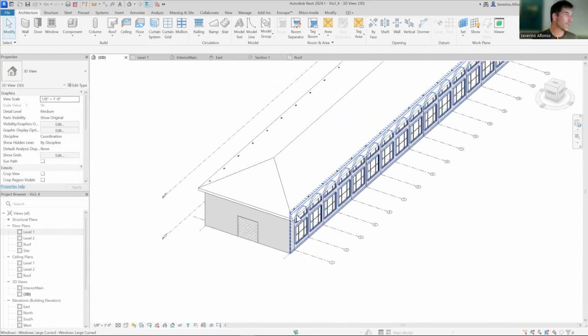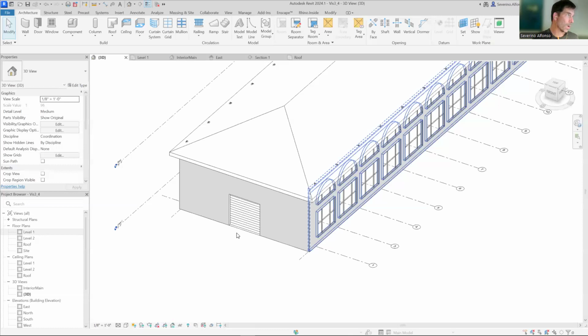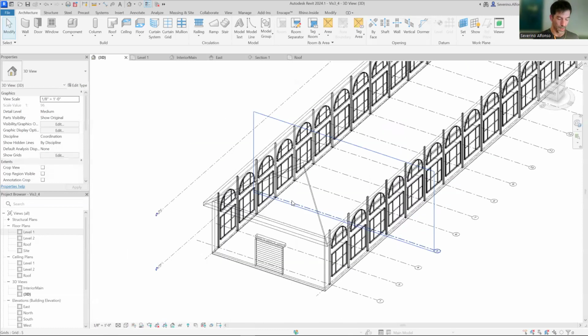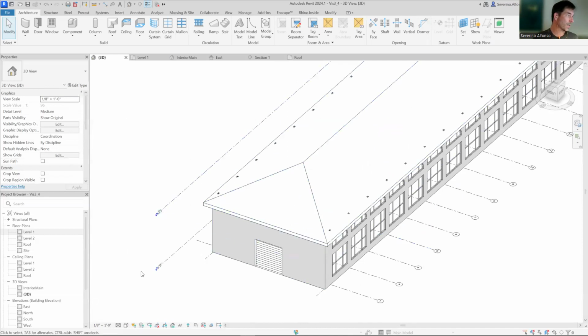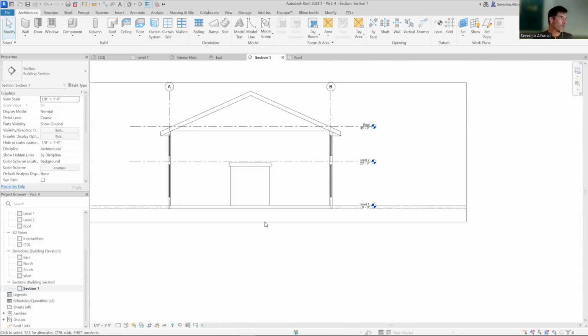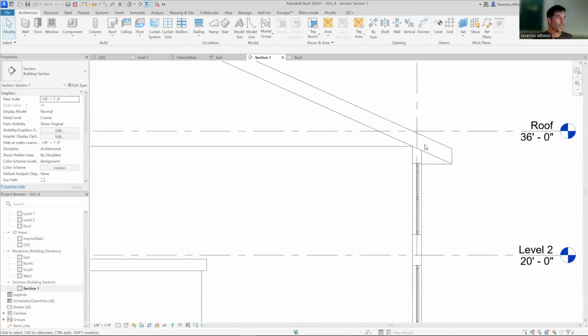You're not going to really see, well, you see them popping up there. We have to adjust that. You say WF for wireframe. See how they're in the middle point. And then HL for hidden line. It's the same as going to wireframe and hidden line here. Okay, so I think again it would be good to go to the section to see what's going on. They're popping up in the back.